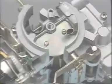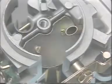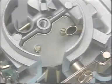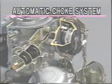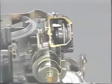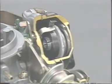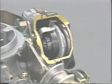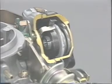The choke valve is located in the primary side air horn. At present, as is shown here, the most common type is the automatic choke system. We will also introduce the electric automatic choke, which is currently in use in most vehicles. The automatic choke is controlled by the contraction and expansion of a bimetal element.